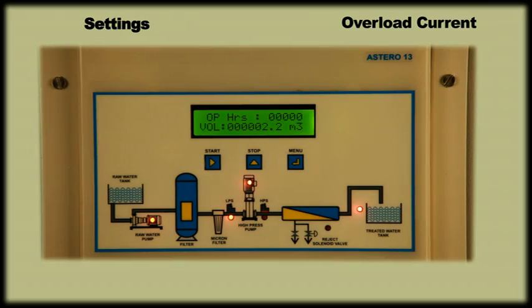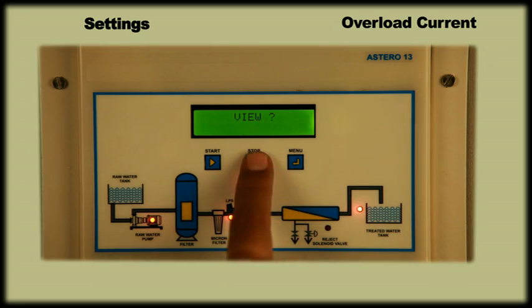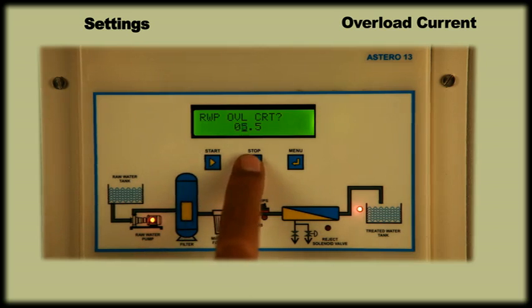Overload current. Let us now understand how to set overload current. One can digitally set the overload current for motors ranging from 0.5 to 5 HP. These settings can be easily done by pressing the menu key and selecting settings by pressing stop key. Display showing settings. Press menu key. Display will show raw water pump overload current. Press menu key again, then display will show previously set overload current. One can change this value using start and stop keys.